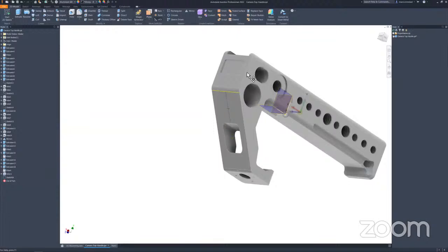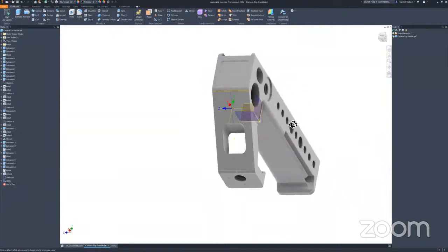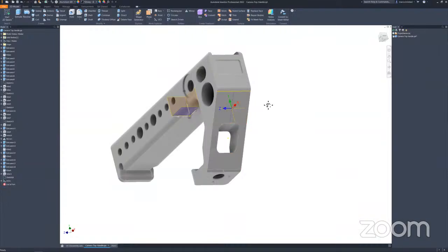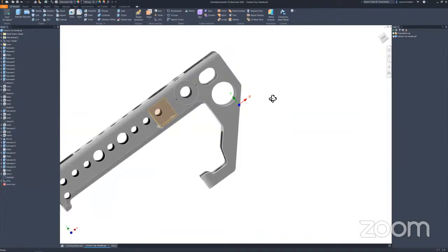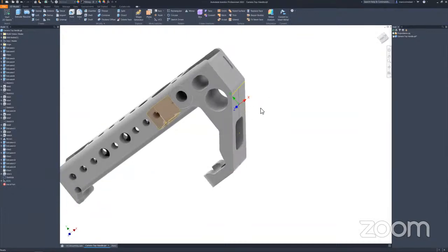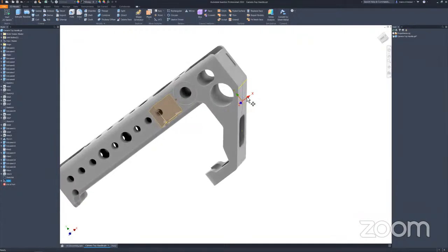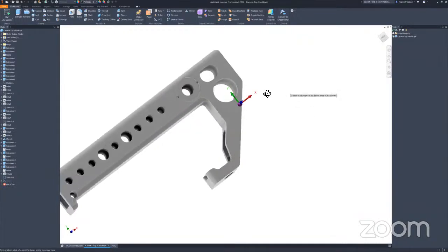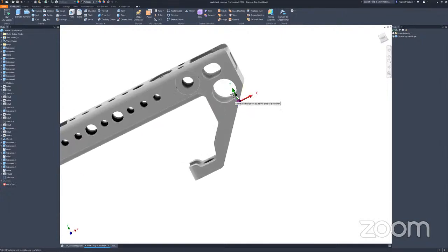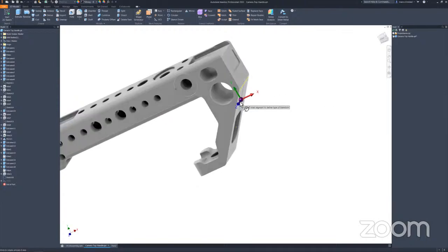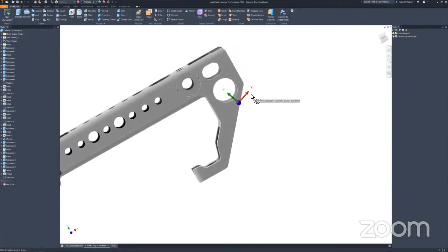You could see I could use this point to place it. And I'm going to click finish since I don't have a defined X point or a defined Y axis point. I'm just going to place it and then select the UCS. Probably one of the hardest things about using them is selecting it. And then I can actually rotate this. So if I see that this isn't quite exactly the direction that I wanted, I can go ahead and just rotate it here. And that looks a little bit closer.